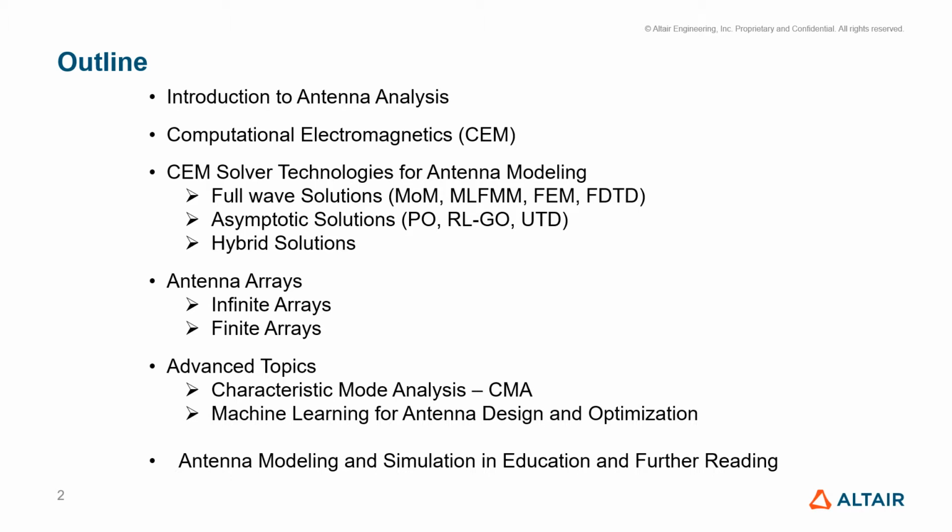Here is a brief outline of today's presentation. We'll start with the introduction to antenna analysis. Then we'll talk about computational electromagnetics that are key to modeling and simulation. And then we'll go a little deeper into various technologies in CEM for antenna modeling, like full wave solutions, like Method of Moments, MLFMM, FEM, and FDTD, and asymptotic solutions, physical optics, ray launching geometrical optics, uniform theory of diffraction, and hybridization of these methods, that is, hybridization of full wave methods with asymptotic methods, and how they can be used for various antenna simulations and modeling.